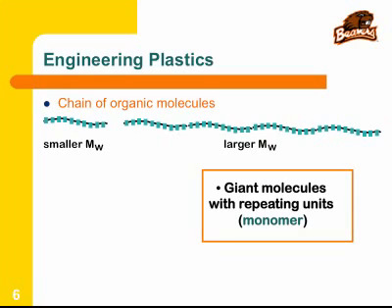Now with water, you have just hydrogen bonding interactions, and so you can easily move the water molecules past each other. But the physical forces connecting the polymer chains, right, are much larger because there are many per molecule. And so for a molecule to separate past each other when it's very high in molecular weight, right, requires more deformation. And that is the principle behind injection molding, right?